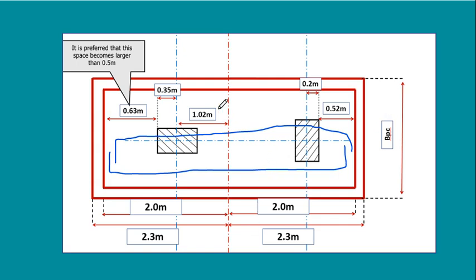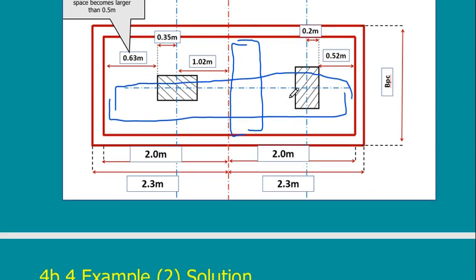What about the other direction? I have here another direction. I need to put a reinforcing steel here. As you see, we said here I have bottom and upper reinforcement. Not like in the case of isolated footing, where I only have bottom reinforcement. But in this case, I have lower reinforcement, upper reinforcement, and in the transverse direction also I will have upper and lower reinforcement. So it is very expensive compared to the other one. So now I need to calculate this steel.